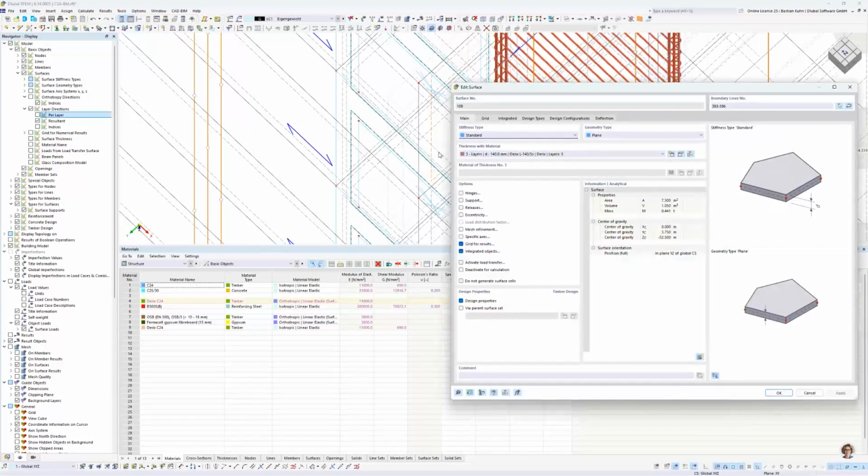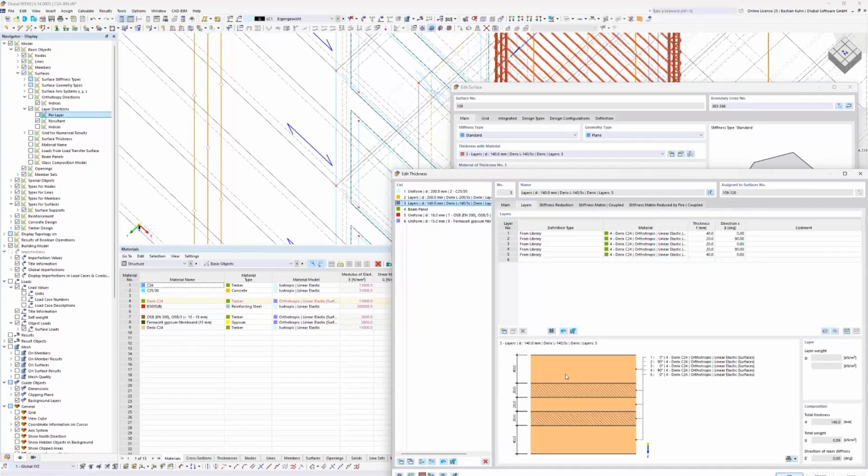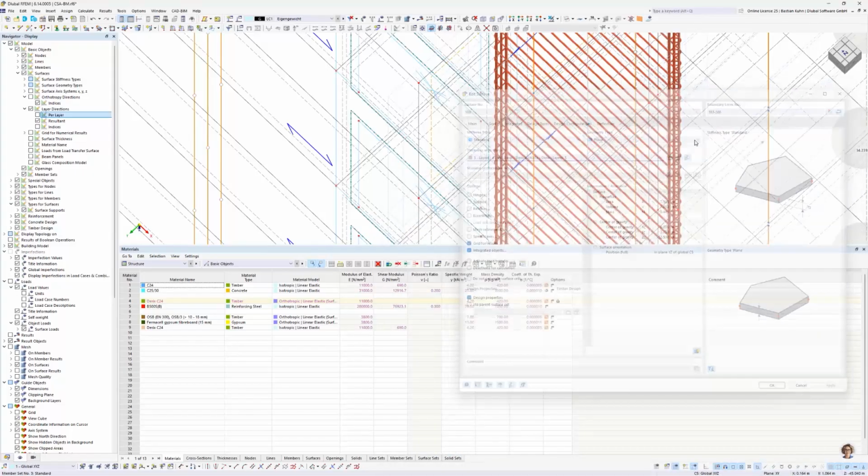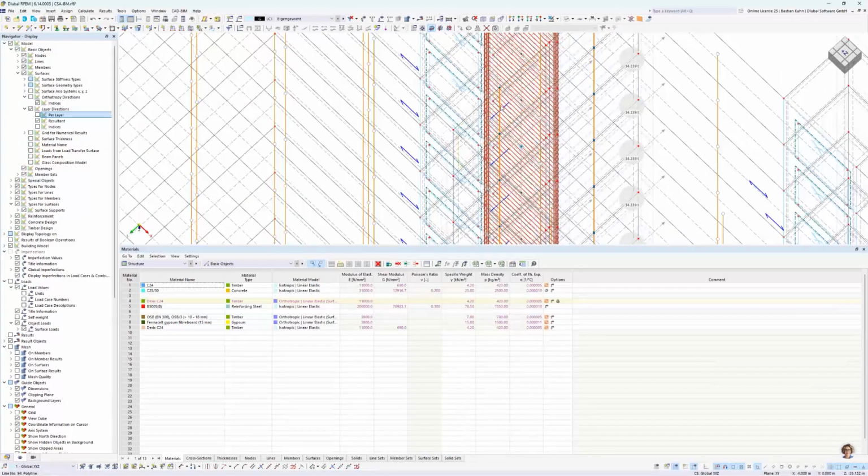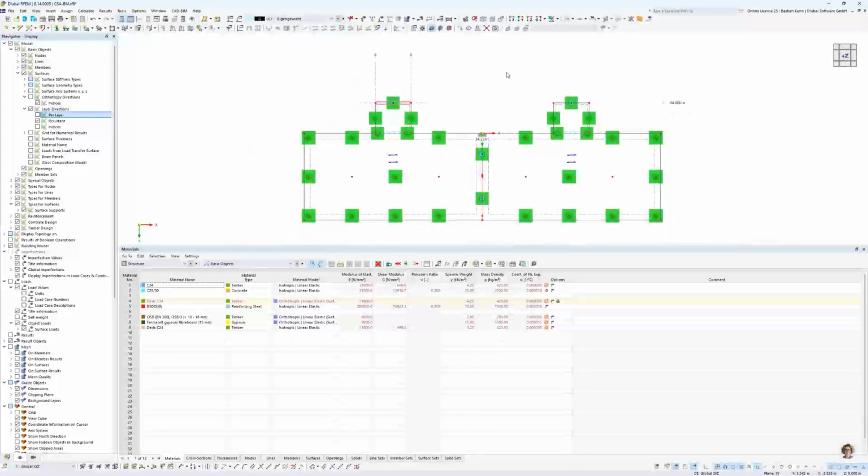So when we look at these ones, to show that again, there are top and bottom layers with 40 millimeters in thickness. And if we span the CLT plate in this direction, you would have an enormous settling in the structure, similar to what you have when modeling a log home, like 20, 30 centimeters or more in such a high building. So that's not what you want, and we have to change it.